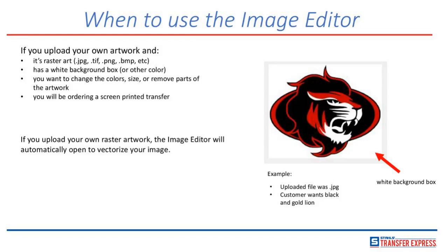Those red areas aren't shapes, they're a series of pixels. So I could sit there and painfully change all the red pixels to gold. That would take forever, and we don't want that. So at the end of the day, when you vectorize this artwork, all those colors become shapes, and then you can click on the red shapes and make them gold. So much easier.